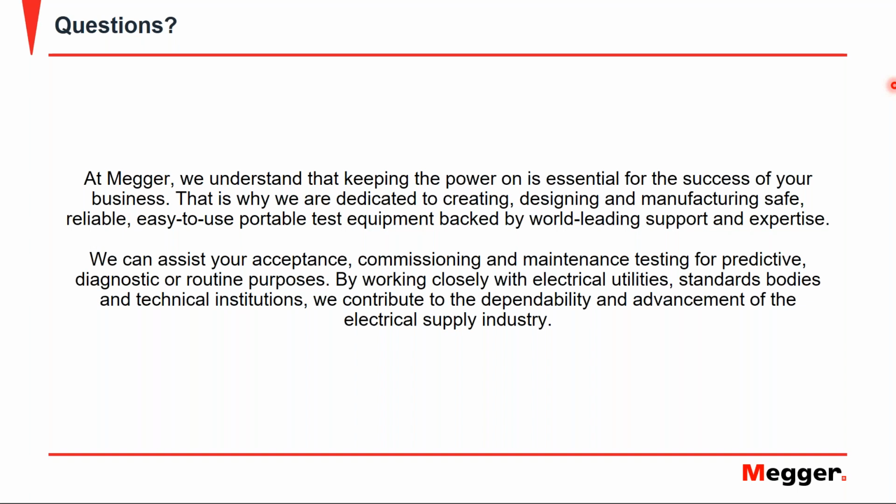Still, there is a chance that there is PD in the cable itself because of bad laying quality. So if they damage the outer jacket and also damage the outer semiconductive layer, then there will be PDs, and those partial discharges will not be as high as PD in a joint, but they will be higher than 20 or 50 picocoulombs. What we have seen in the field is that those levels are 100 picocoulomb, 150 picocoulomb, and you can still identify them with the offline test in the field.